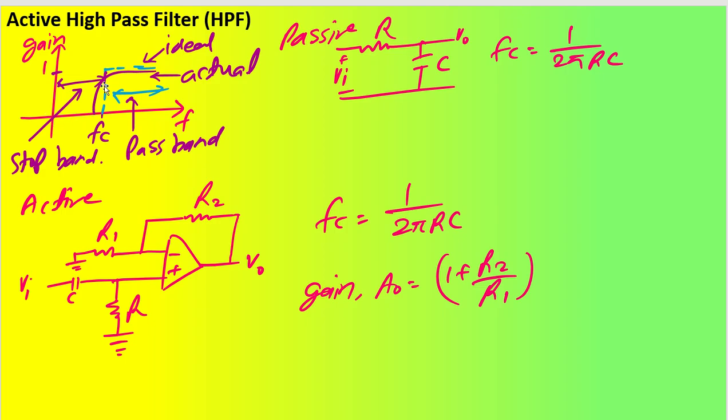Let's say it starts from this. This is the purple color that is there. That is high pass. Before that, this will be a stop band, and after that, this is going to be the pass band, which is where frequencies will be allowed. And the little bit bluish color is actually the ideal filter, with a sharp cutoff, you can see a square. Designing a filter like this will be a little tough because a first order filter will be a little over rolling kind of thing. However, with a very high order filter you can come closer to ideal.